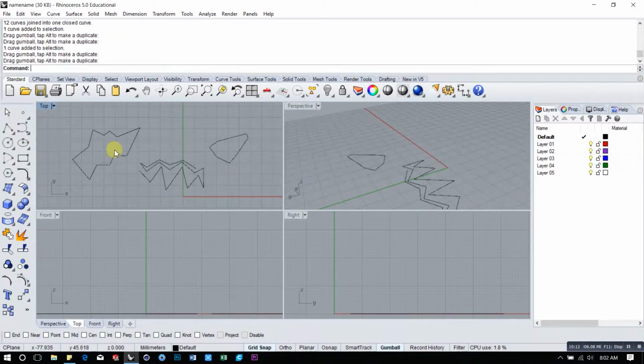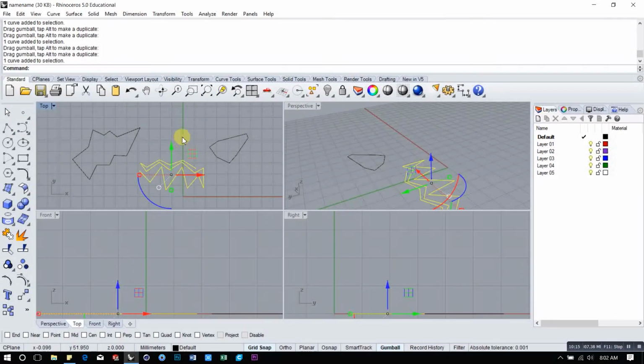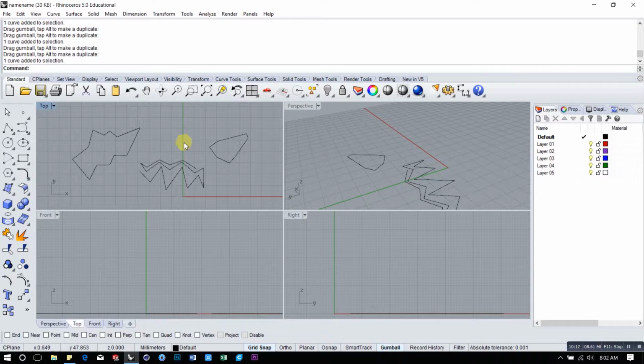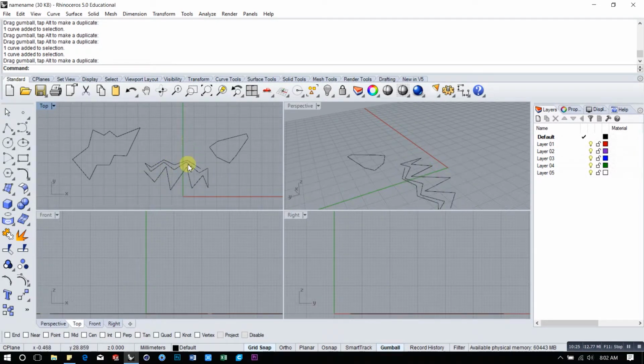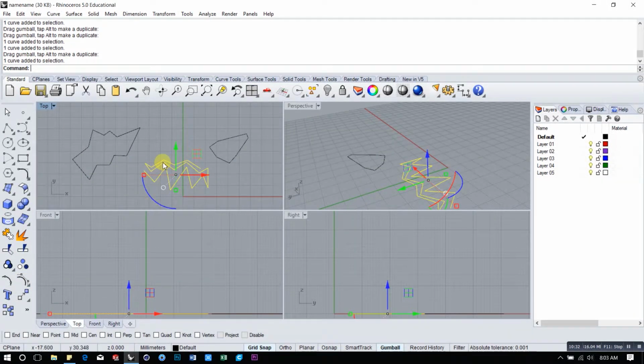We're creeping up on 10 minutes, so I kind of want to shut it down. There was one thing I wanted to talk about, which is just edit points. I kept talking to you about how we edit a line that we've already drawn. Right now we can move it around in 3D space, but can we edit it? Can we change the look of these lines? And you can. It's down here with this button right here, points on.